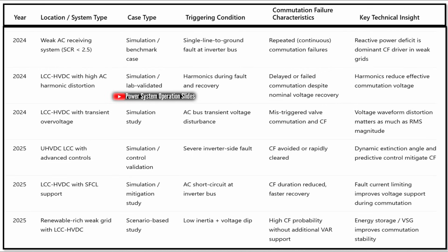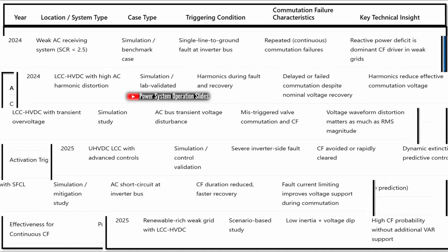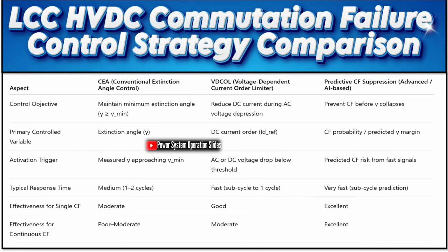Optimizing operating conditions provides another avenue for commutation failure mitigation. Proper transformer tap settings ensure appropriate converter valve side voltages, maintaining firing angles within optimal ranges and preventing over or undermodulation. Accurate firing angle control, implemented through individual phase control (IPC) or equidistant pulse control (EPC), ensures proper commutation sequences and preserves commutation margins.